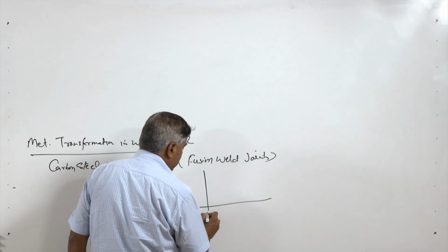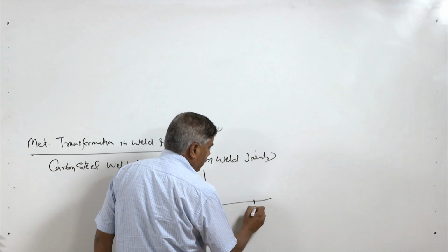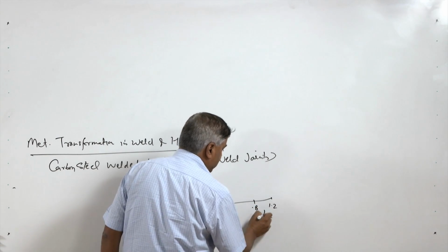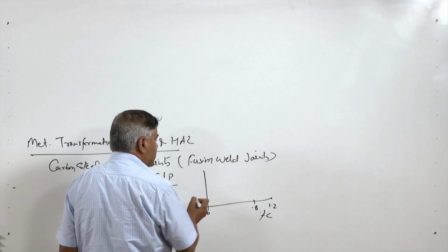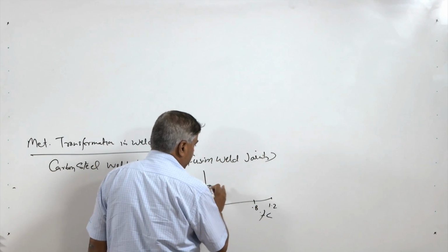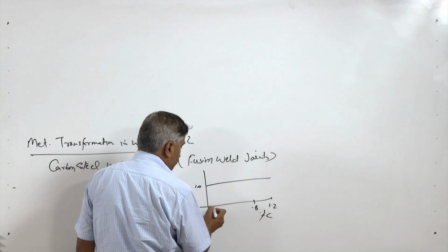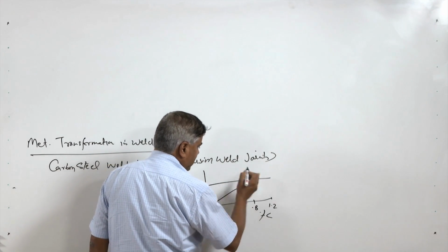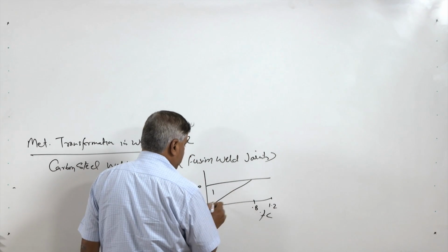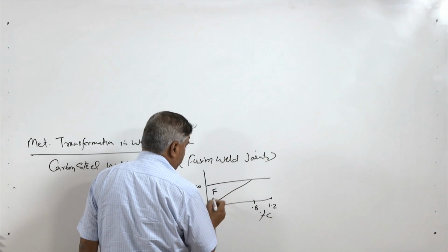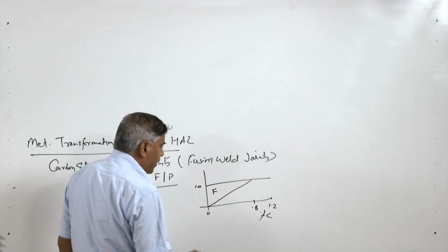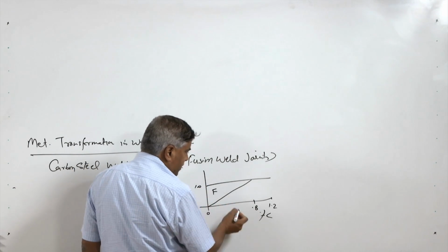Normally, if we see 0% carbon content, 0.8 percent carbon content and 1.2 percent carbon content on the x axis, and here schematically we show the structure, in the first half say 100% ferrite. When the carbon content is 0, the entire system is ferritic and the pearlite is 0.